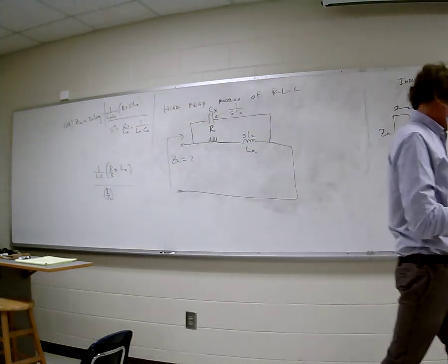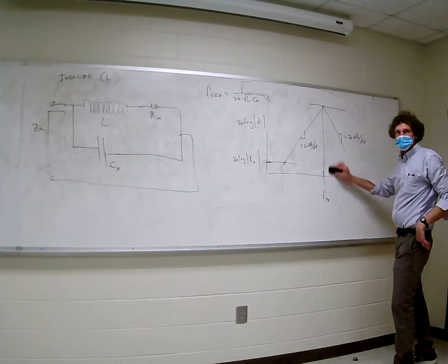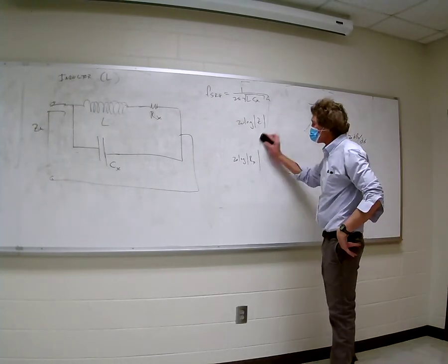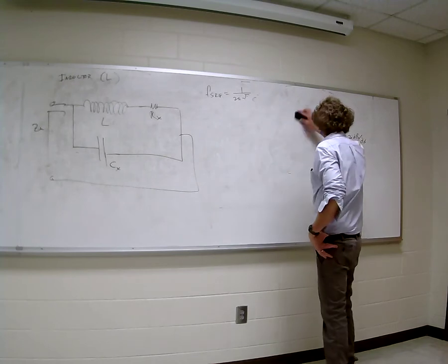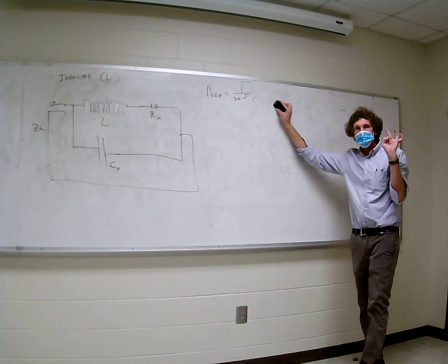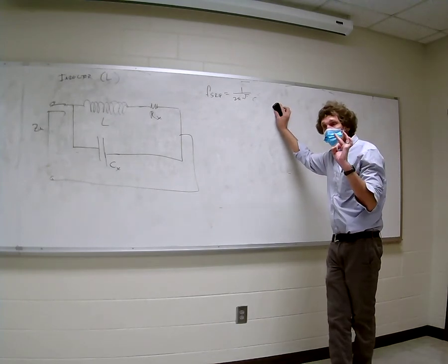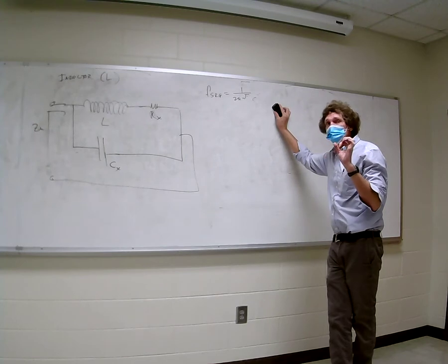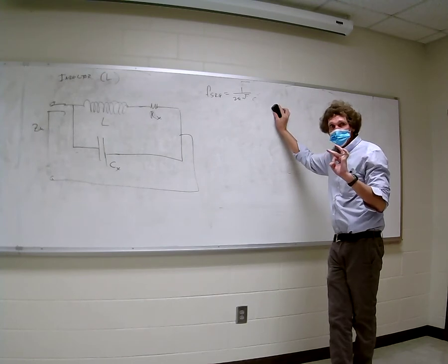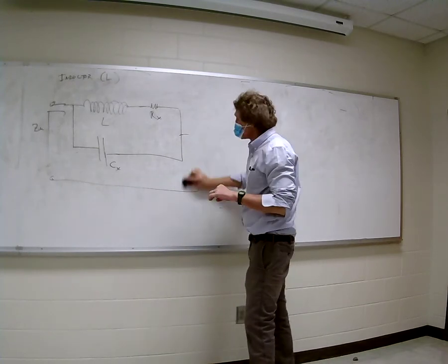And I have my own take on capacitors. Capacitors come in every shape and size you can imagine. You familiar with these really small little flat mica capacitors that are like picofarads, tens of picofarads, even sub-picofarads, right? The lead length themselves can significantly change that value. Just realize that.